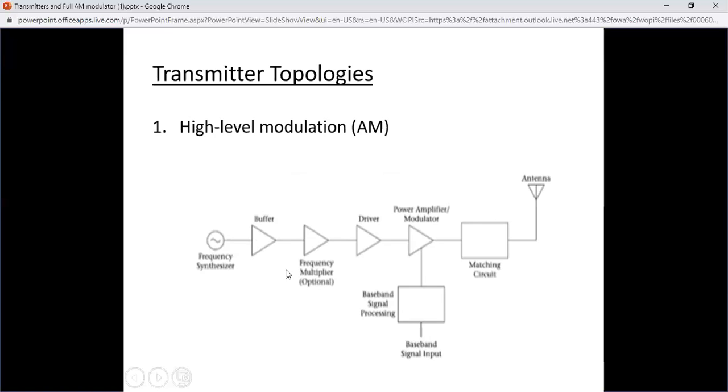To be clear, matching or power matching is when the input impedance has to be equal to the output impedance of the previous block. So the Z output, or the output impedance, should be equal to the conjugate of the Z input. It's also used to reduce the noise and the harmonics produced. Without matching, there will be losses and the maximum power transfer will not be achieved.